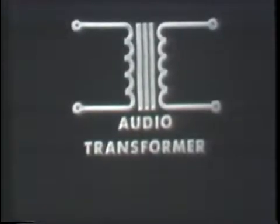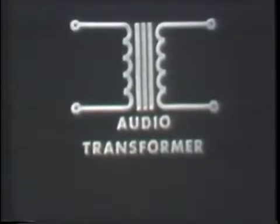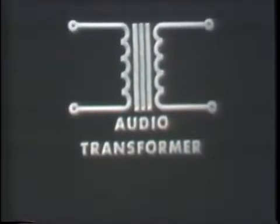Like the power transformer, the audio transformer, too, is usually constructed with an iron core. Well, at frequencies above 20,000 cycles per second, the RF transformer comes into use. At these frequencies, hysteresis and eddy current losses in an iron core become so great they have to be prevented. Therefore, RF transformers generally have an air core.